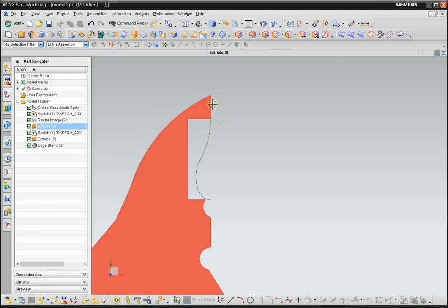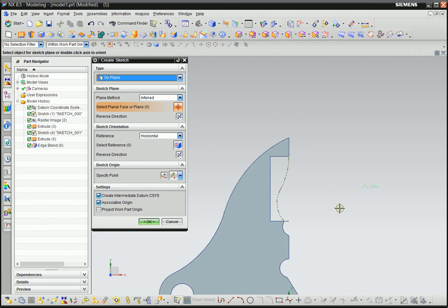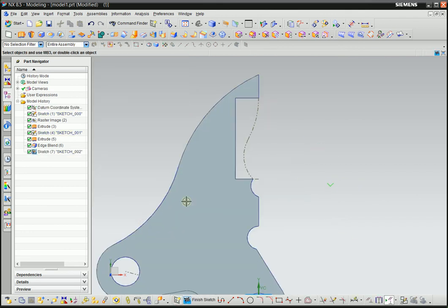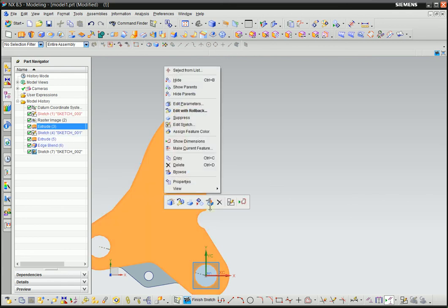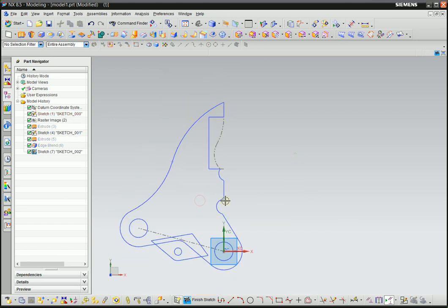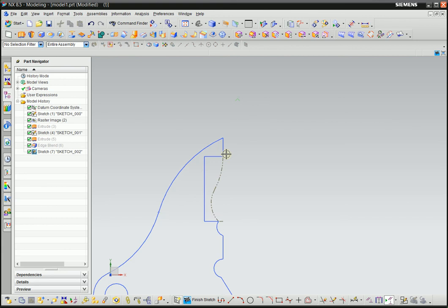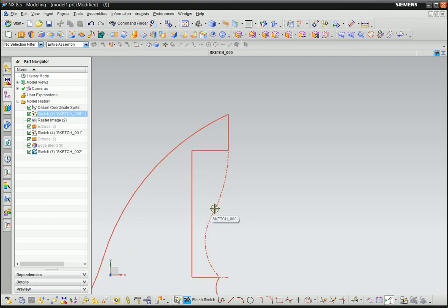So now we can go ahead and do the teeth. We need another sketch. Okay, again that's YX. Click OK. And if you don't like this solid piece here, you can right click and hide this. And actually we don't care about that. Okay, so now we have a teeth shape, and what you can do is we can get this curve.